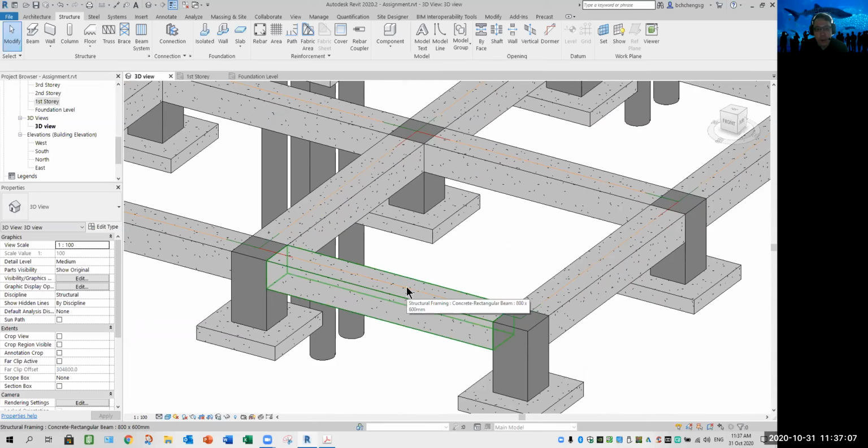This is what we call the analytical system, which will create a kind of overlapping with our modeling. So for the meantime, if you see something like this and you wish to disable it, you simply check below here: Hide analytical model, uncheck. Then it disappears. So when you make amendments to your model later on, you won't accidentally select it.